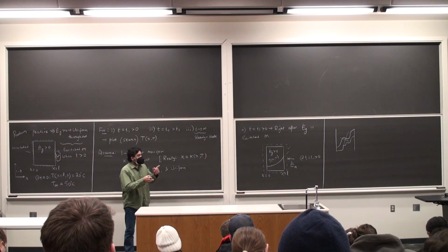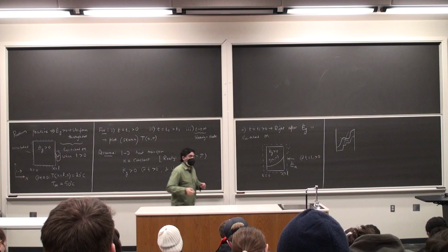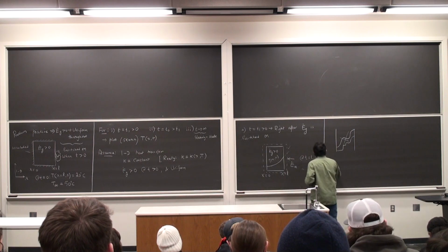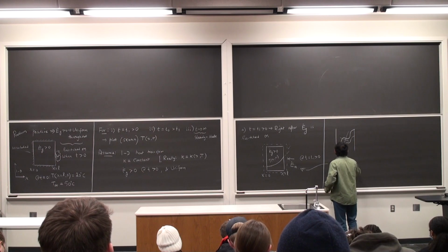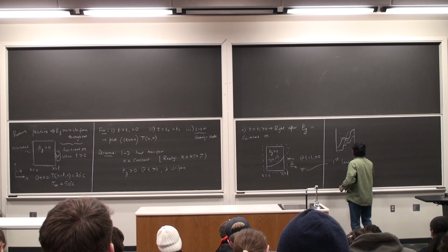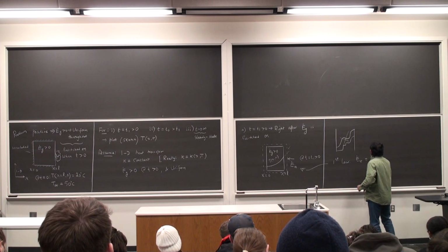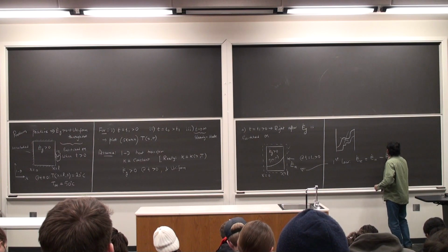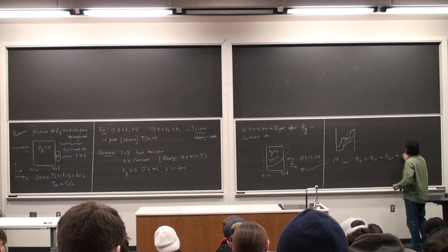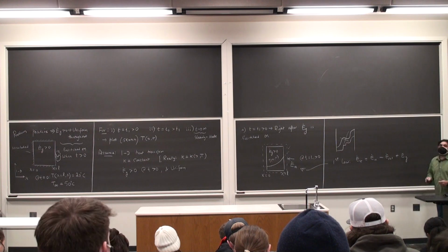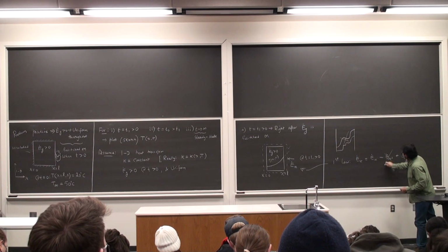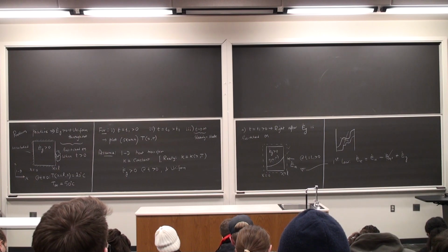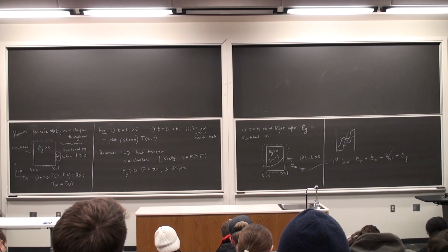So if I write the energy balance equation of the first law, E dot stored equals E dot in minus E dot out. Mind you, we have positive energy generation, so that is plus E dot G. E dot out is 0, as we don't have anything going out of the other side.